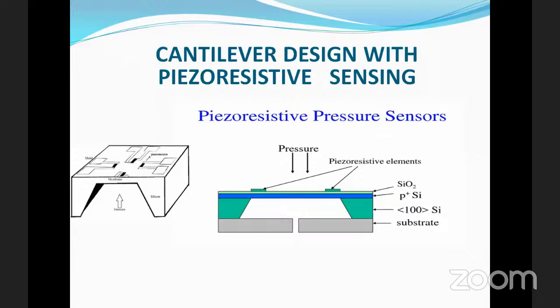A coating of silicon oxide layer is made, and over that a coating of sacrificial layer, that is phosphosilicate glass, is made, and this sacrificial layer can be suitably etched out using pattern transfer techniques. And the final cantilever, that is a structural layer, is again coated on the sacrificial layer by suitable patterning methods, and the removal of the sacrificial layer creates the microstructure, and that is useful for development of cantilever based biosensors.